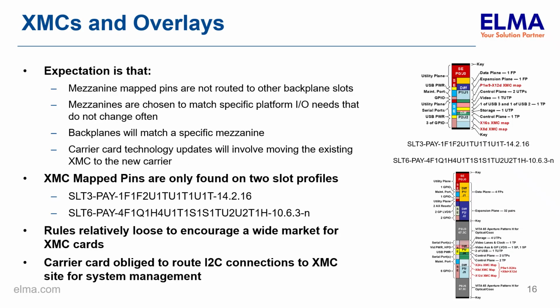XMCs are an important part of the SOSA technical standard. Not that the standard defines much in the way of specific rules or definitions for XMCs themselves, but because XMCs provide a way to bring specialized outside connectivity right to the plug-in card. However, there are certain expectations that drive the few rules relating to XMCs, including that mezzanine map pins are not routed to other backplane slots.